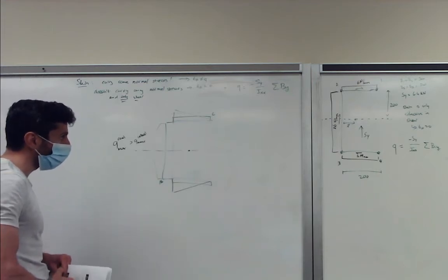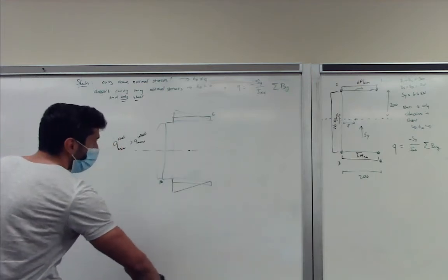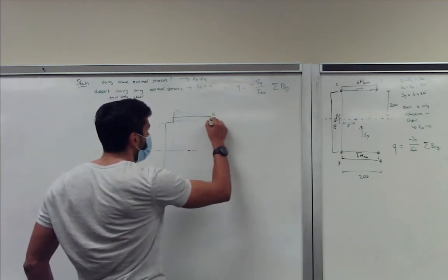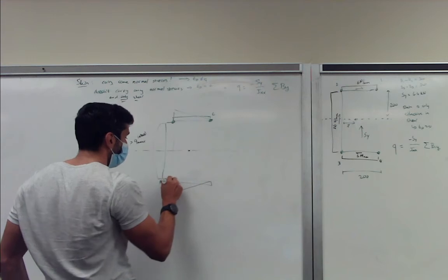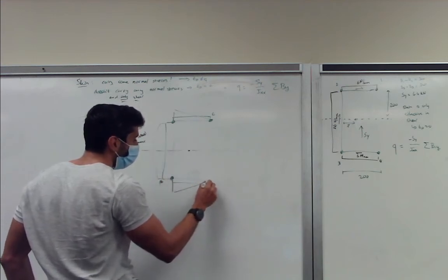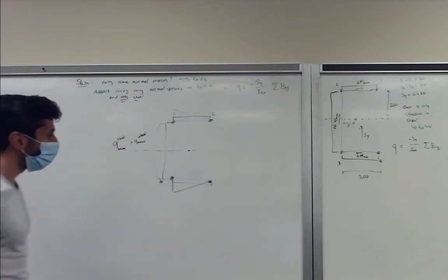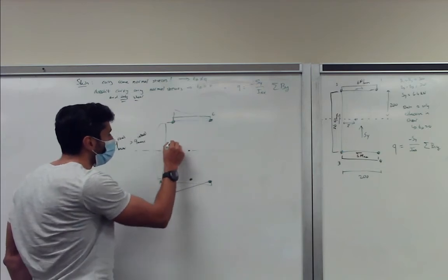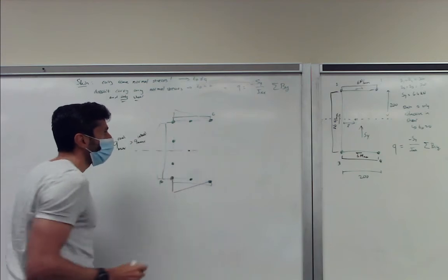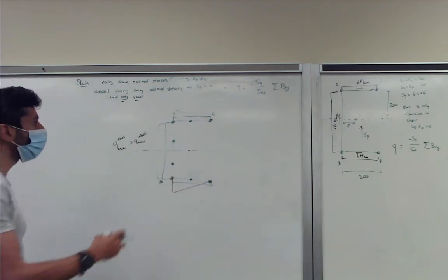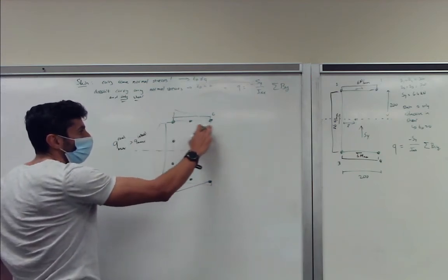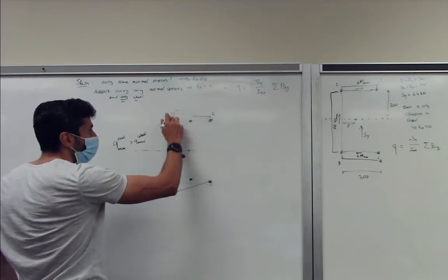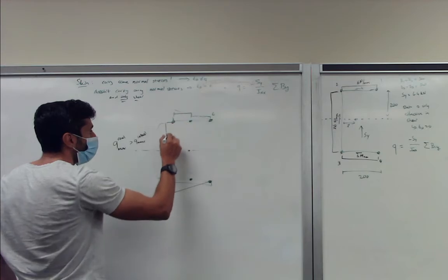solution for our problem. There are a couple of ways you can improve upon that solution, instead of having 4 booms, by increasing the number of booms. So we could add another one here and 2 more here. What that will do is the same thing: you will have your constant shear flow between booms, and here we'll basically add another step in it.